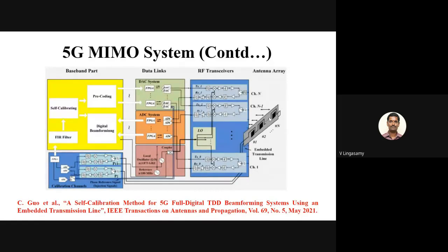So why are they defining that? For example, if you want to communicate, it basically boils down to EIRP calculation, basically link budget calculation. So if you want to cover 100 meters, what should be the power level of my radio, because the signal will experience path loss in the area, right?